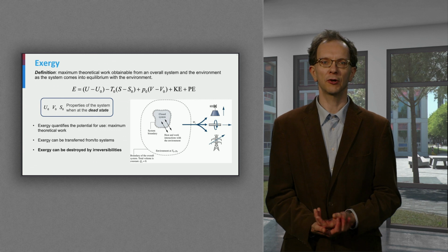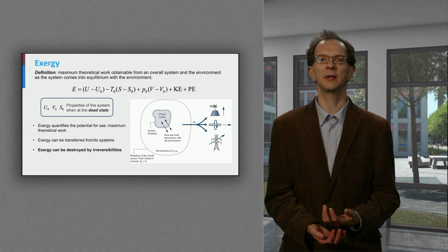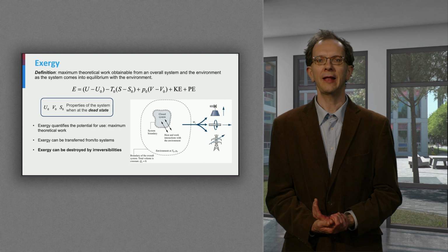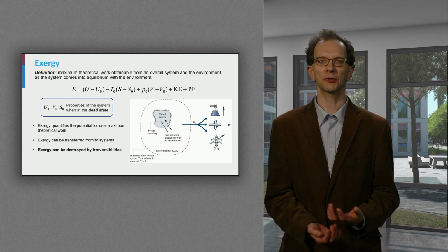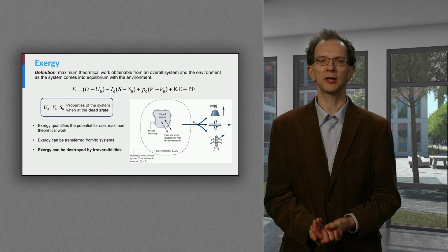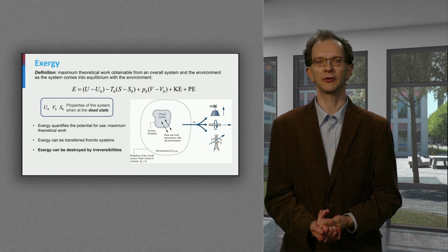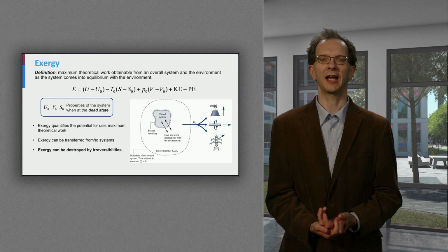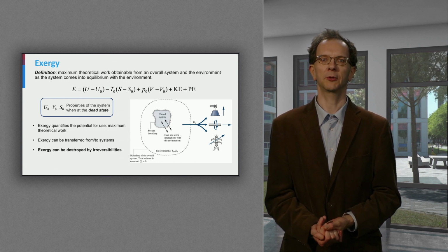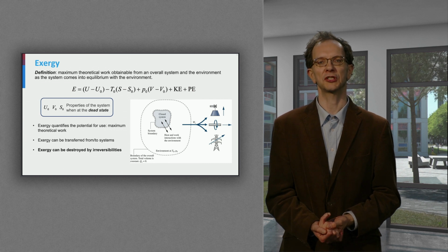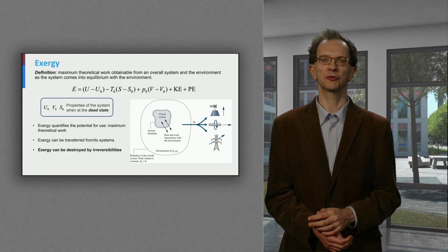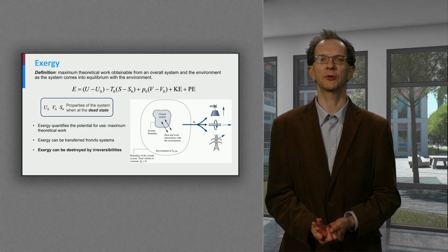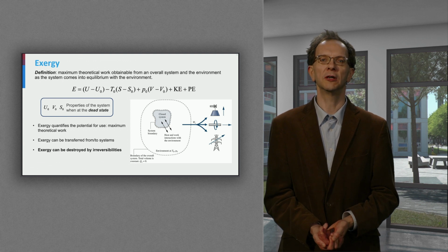It is important to note that exergy can be destroyed by irreversibilities such as friction in the system. Having zero exergy destruction is not possible in practice, as it only applies to processes that are infinitely slow. It is the task of an engineer to make sure that the exergy destruction of a system is minimal given a certain production rate of the system. Exergy destruction is closely related to entropy production in the system. Multiplying the entropy production with the surrounding temperature T0 gives the exergy destruction.